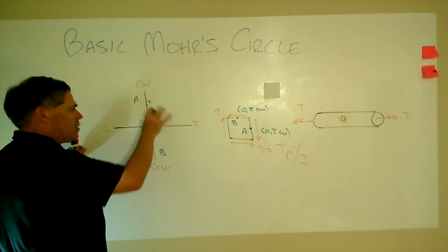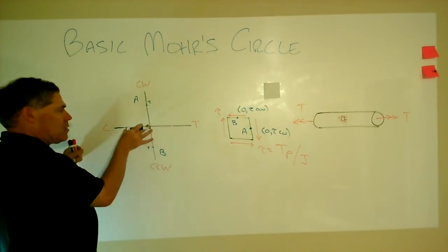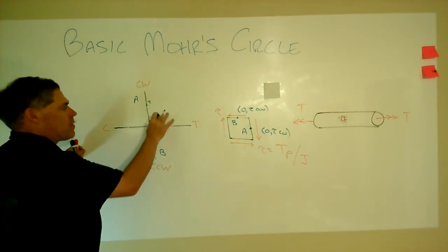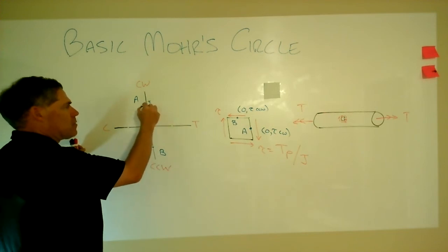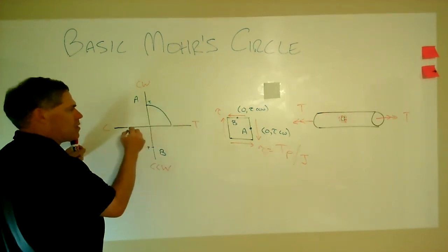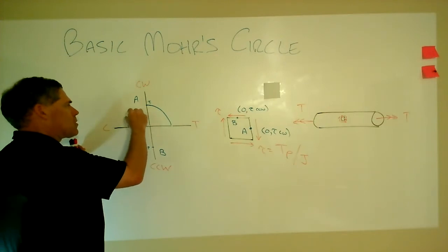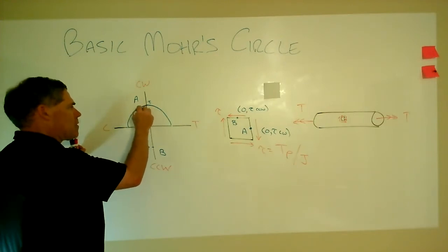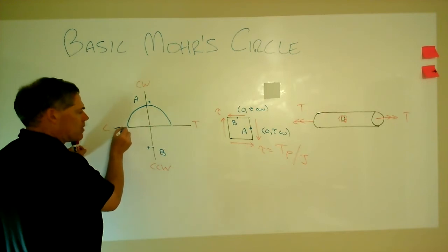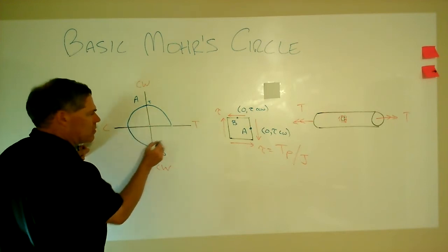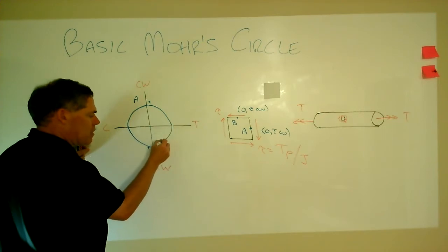So I can get in these other points, and sometimes it's even handy to get some intermediate ones so that you can draw your arc. Get your circle template out to do this. But if you just want to sketch out a possible answer, this is how you go about doing that.